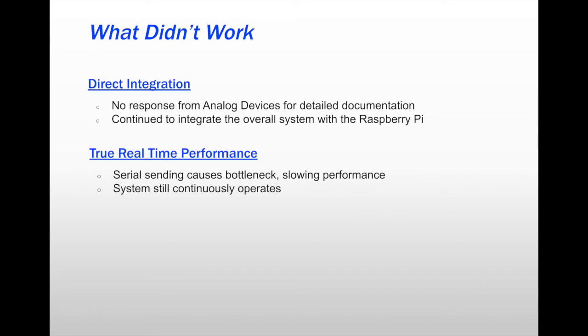This created a bottleneck in the system's processing scheme, as the UART interface is not nearly fast enough to transmit the large amounts of data required for even a single frame, which meant that it would be much more difficult to implement a live visualization process that would be supplemented by a continuous and fast stream of data from the evaluation kit. Ultimately, we opted for continuing with the UART implementation and added the functionality of storing multiple frames of data to be continuously displayed to emulate the visualization process of an ideal system.